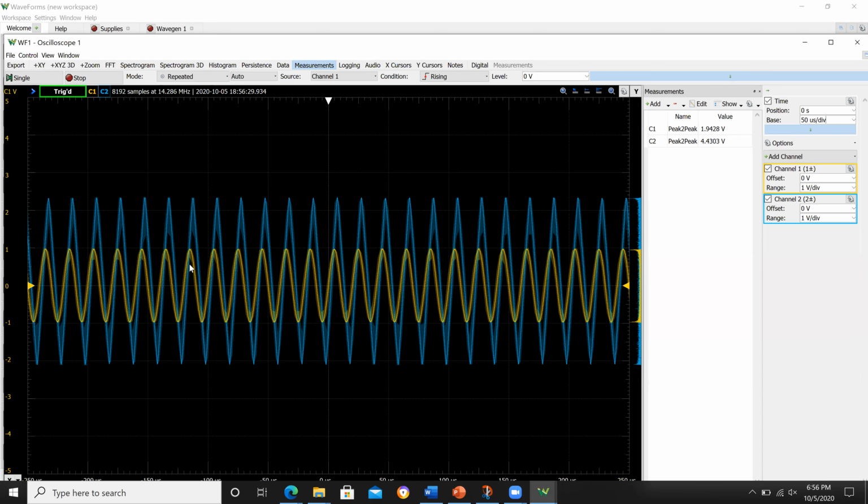What creates a voltage according to Ohm's law? So it's V equals I times R, right? So R is fixed, that's our resistor that we're dropping a voltage across, and I can change. Well, how fast can I change? Well, in order for this circuit to duplicate this sine wave, but in a gain version, right, on way up and down, it's got to be able to source and sink a lot of current really fast to create that gained up version of the input.